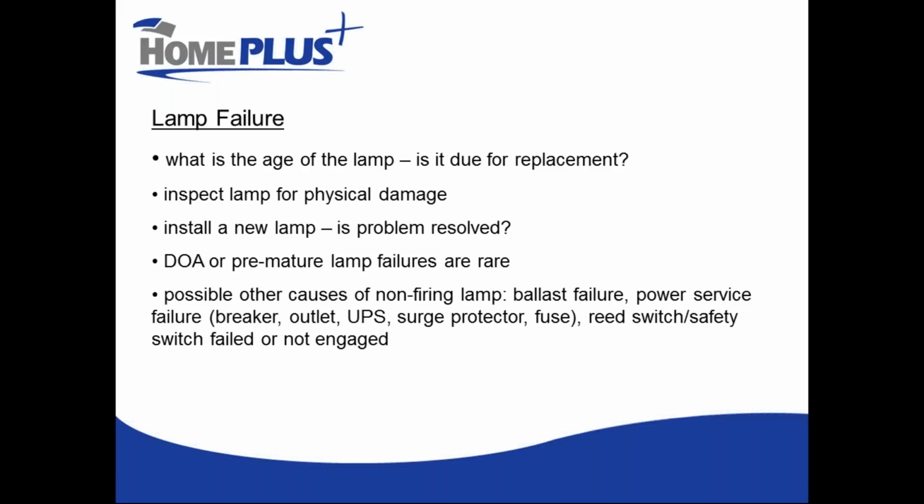You may also need to provide chlorination that's high in order to get the 0.2 chlorine residual at the end of your distribution. If it's 5 miles away, especially, or through a long distribution pipe that has old mineral buildups in it and that sort of thing, chlorine is going to continue to dissipate between your water treatment plant and your customer at the very, very end of the line.